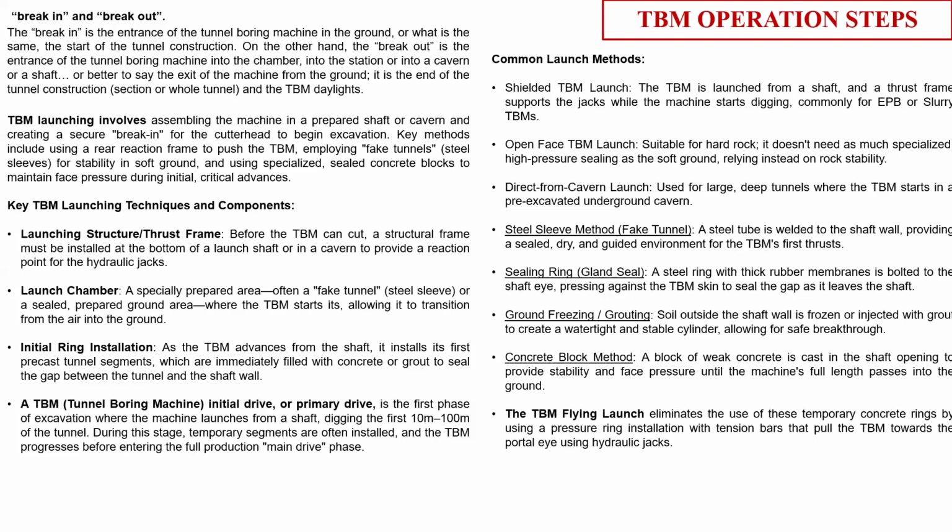So first of all, how are we launching the TBM? The launching of the TBM, as I told you earlier, can be done through a shaft, or it can be launched from an open ground or a curtain cover ground, the ramp region. In lots of projects you see a TBM launching shaft. If it is a TBM launching shaft, then you have to prepare the shaft. That shaft can be a temporary shaft or a permanent shaft.